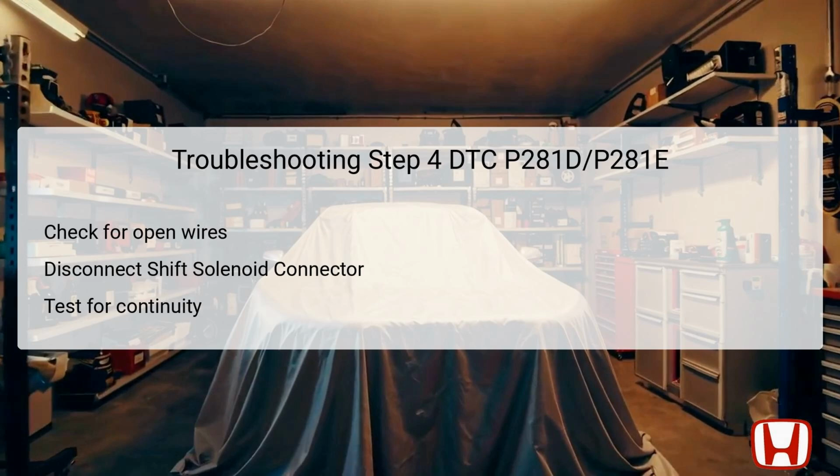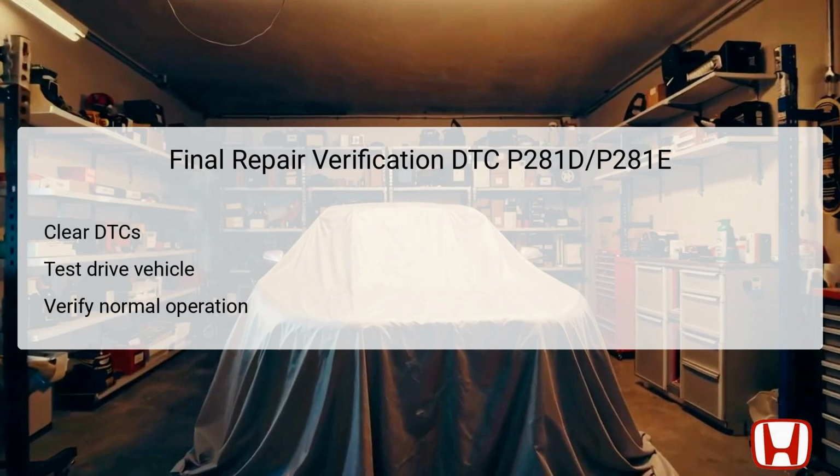However, if no continuity is found, it suggests an open in the wire between the shift solenoid valve OP and TCM, necessitating repairs in that wiring to clear the faults indicated by DTC P281D and P281E. After completing all necessary repairs and replacements related to DTC P281D and P281E, the final repair verification is essential to ensure everything is functioning correctly.